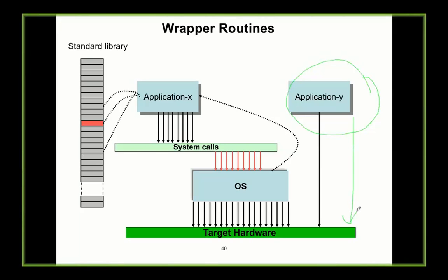The problem with this kind of program is that a small change means the entire application has to be rebuilt. So it's not very portable. You have to keep rebuilding for a small change. For example, if on a particular port, instead of a 30 microsecond delay, you have to generate a 60 microsecond delay, once again you have to go and make changes in the code and rebuild the entire application. You have to again find the right number which will sit in the timer, and then rebuild that application, convert to hex, and then dump that by using burner tools.